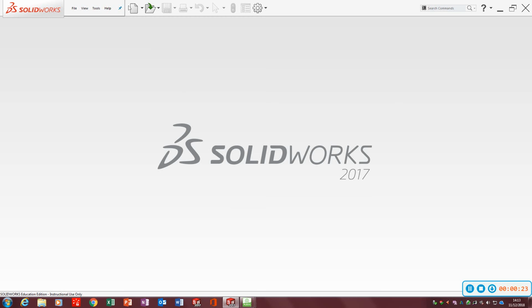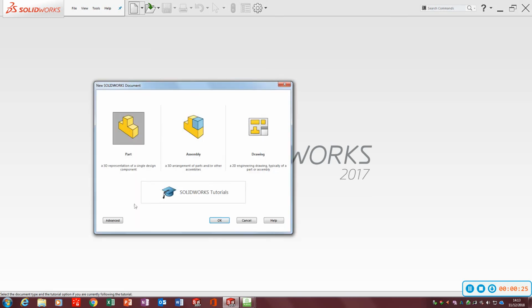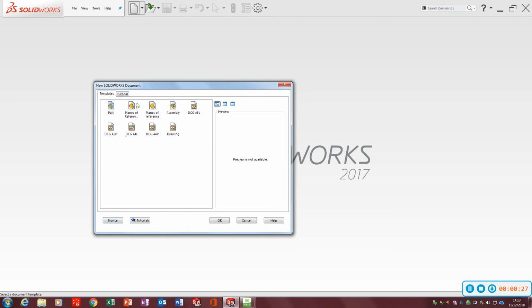Okay, so I'm going to go New, then Advanced, and I'm going to go Planes of Reference. Okay, so I have two of these. If you don't have this, will you just call me please? Okay, so I'm going to go Planes of Reference.